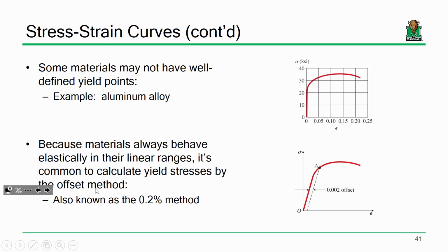Now, one of the things the video was talking about is this concept of yielding. Yielding is going to become a very useful limit in terms of design. For instance, I'm designing this shaft for a transmission for a car or what have you. I'm designing it out of steel. I want to make sure that everything behaves the way I would like it to, so why don't I say the stresses shouldn't exceed the yield stress, okay?